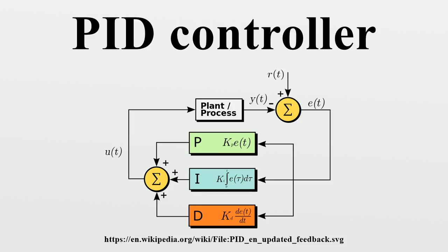In the interest of achieving a controlled arrival at the desired position in a timely and accurate way, the controlled system needs to be critically damped. A well-tuned position control system will also apply the necessary currents to the controlled motor so that the arm pushes and pulls as necessary to resist external forces trying to move it away from the required position.